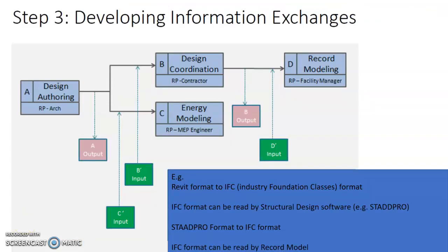For example, part of the workflow for BIM users in this VDC project requires the design authoring, let's say from the architects, for the model to be linked with the design coordination model, for example, and the energy model, and finally from the design coordination model to be linked with the record model.